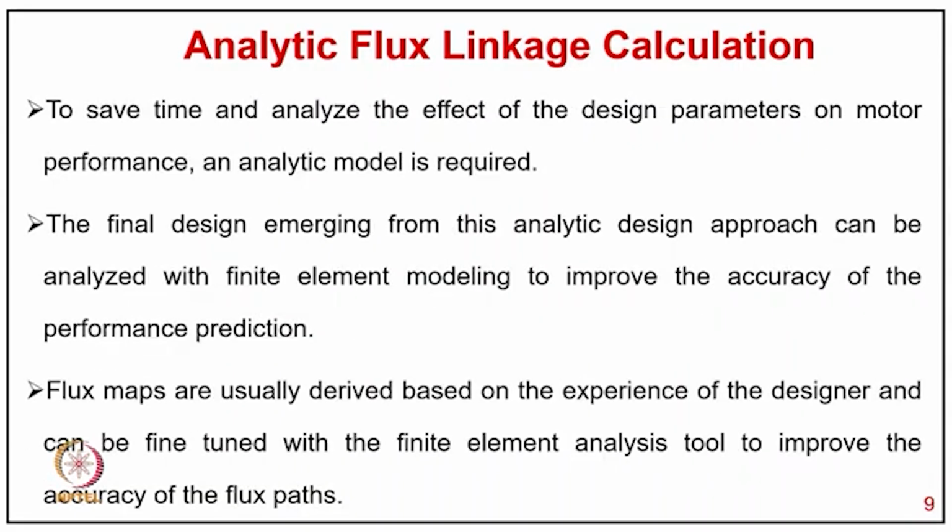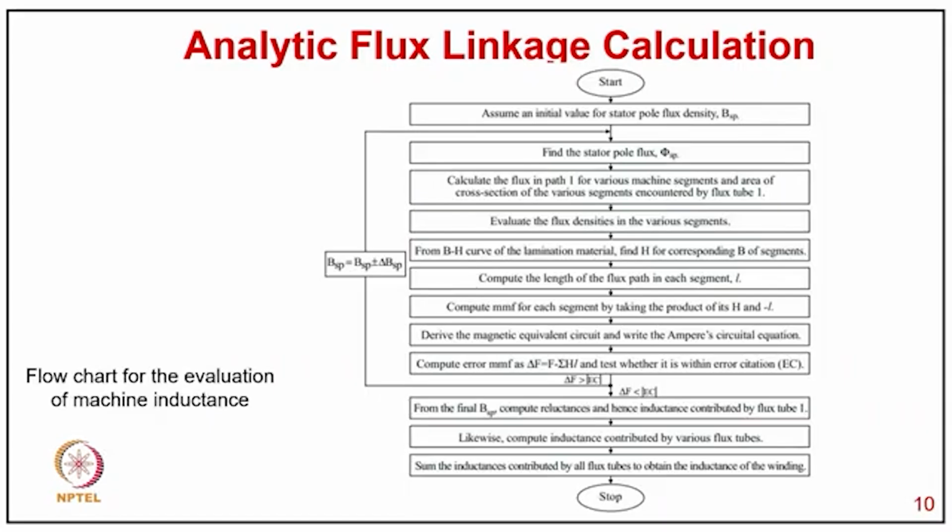To save time and analyze the effect of design parameters on motor performance, an analytical model is required, and the final design emerging from this analytical approach can be analyzed with finite element modeling to improve the accuracy of performance prediction. Flux maps are usually derived based on the experience of the designer and can be fine-tuned with the finite element analysis tool to improve the accuracy of the flux path. Typically, the flow of this analytical flux calculation is given in the flow chart here.